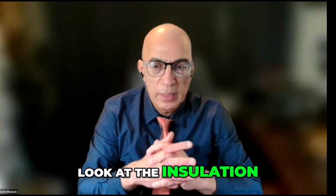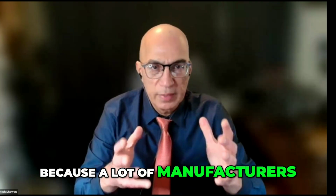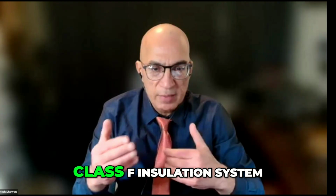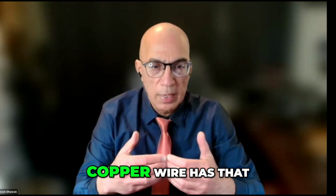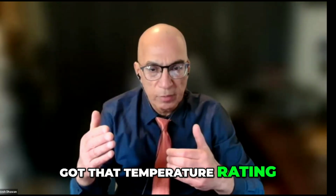You also have to look at the insulation rating of your motor, because a lot of manufacturers, when they manufacture the motor, certify to a UL insulation system. So you can have, let's say, a class F or class H insulation system, where you want to make sure your copper wire has that insulation and that temperature rating as well.